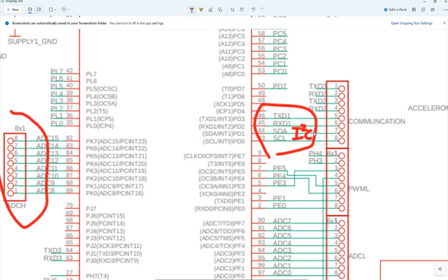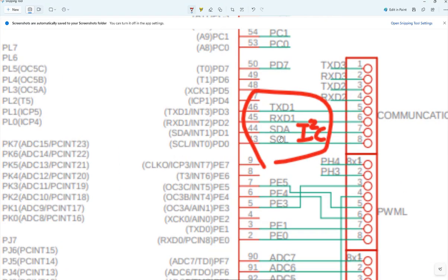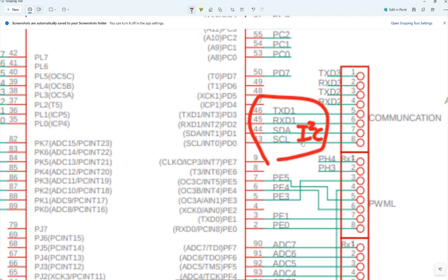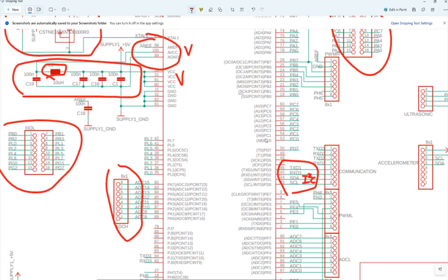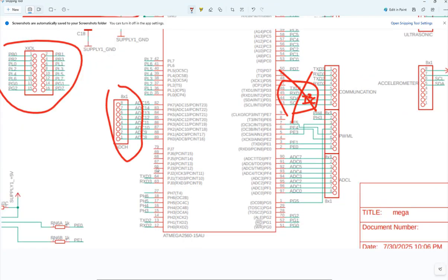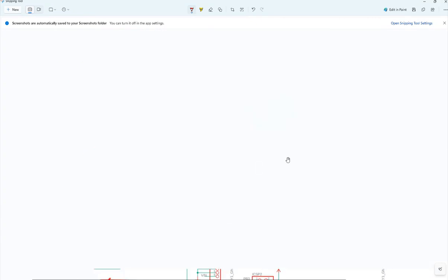But I2C is slow and it takes fewer pin resources, and also it's able to do long distance communication. But SPI is too fast. Over long distance there will be a lot of parasitic capacitors, and the signal will get shorted to ground. So you need these parts, but you don't need I2C if you're not using it, and then just pick up the pins you need and short them to your sensors and modules. You need 2 modules, at least 2 modules. What else?